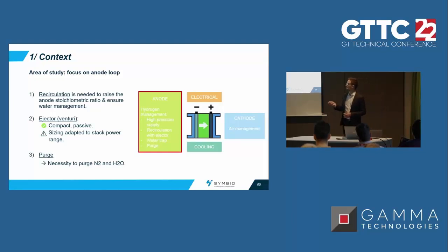In our case, the recirculation is done with an ejector. It's a venturi, so it's compact and lightweight. It doesn't need to be powered. So this is a good solution. However, the sizing is critical, so I will dive into detail on that in the third part.